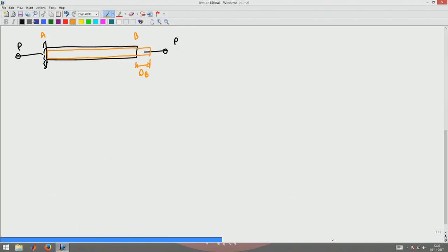So, the displacement field I assume is, a displacement field u, which is, I want this displacement to be delta B at a distance L from the end A. Say the length of the bar initially was L. Let us assume a coordinate system, let us assume this is x, this is y and this is z, then it is getting displaced by amount delta B along the x direction at x equal to L. And at x equal to 0, I know that the x component of the displacement field is 0.